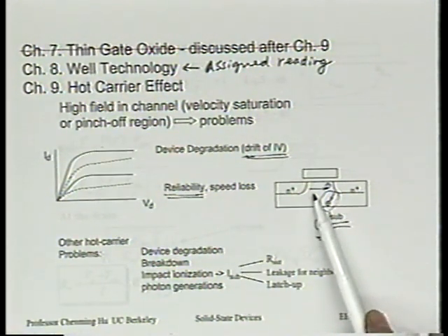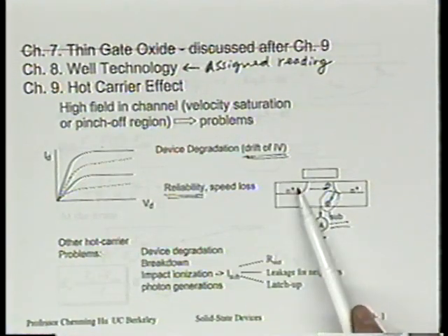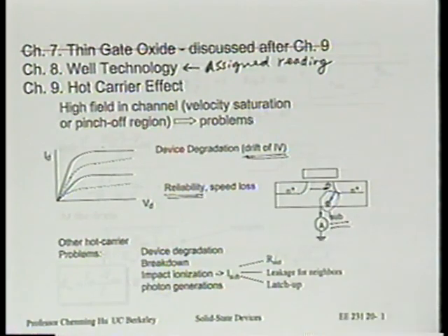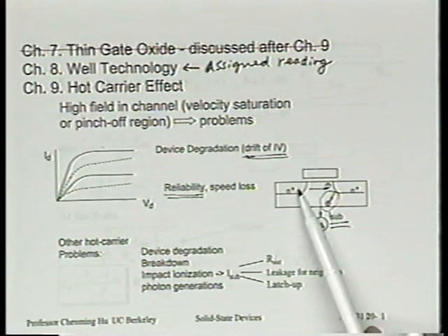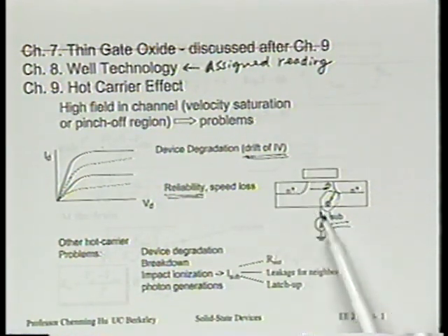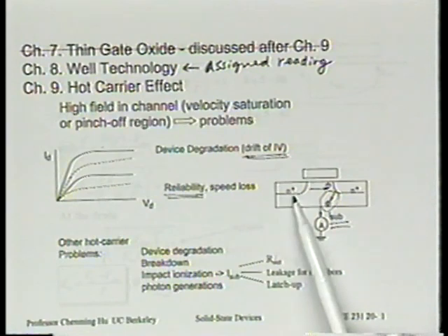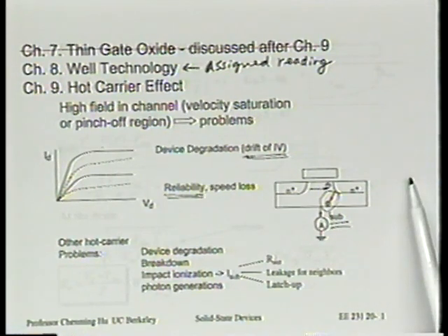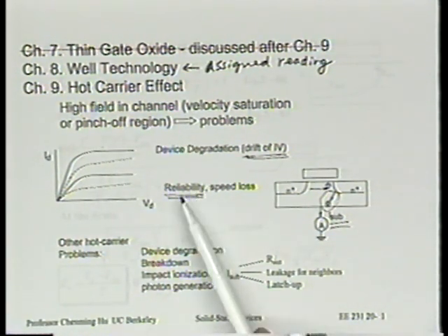The substrate current actually could also create enough body bias such that the source and body junction becomes forward biased at 0.6 or even 0.7 volt. At that kind of forward bias, electrons will actually be injected from the source into the substrate. Once electrons are injected into the base, they can simply diffuse to any other p-n junctions and other drains of neighboring transistors.